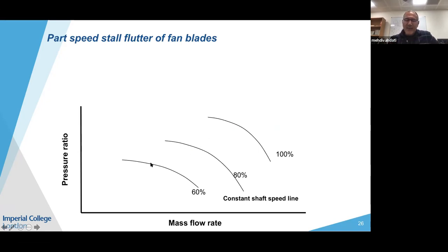So taking it, for example, that I'm a fan blade designer, first thing is I put the constant speed characteristic at some running condition. For example, this is sort of landing, this is sort of takeoff, near taxiing, and this is cruise. And on top of that, I determine a working line. So if everything goes well, as you accelerate the fan blade, you just go up this working line, and this is determined by the geometry downstream of the blade.